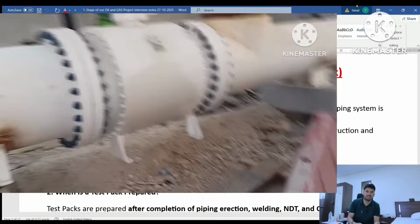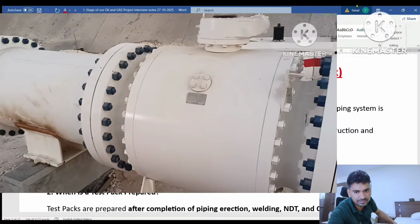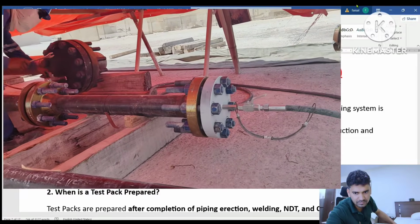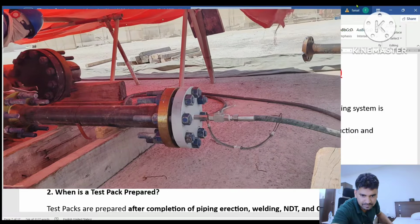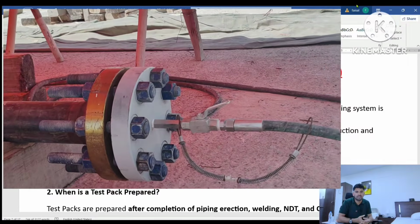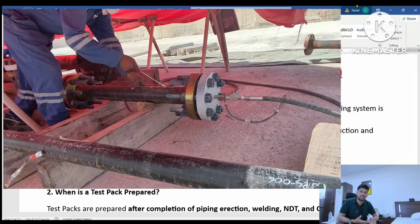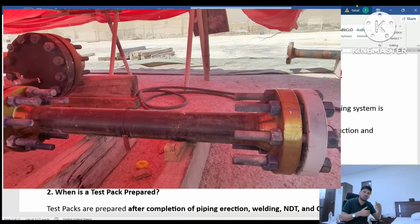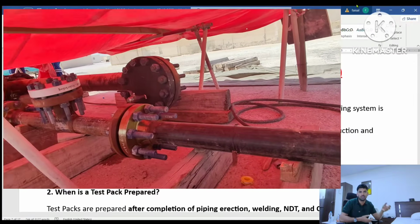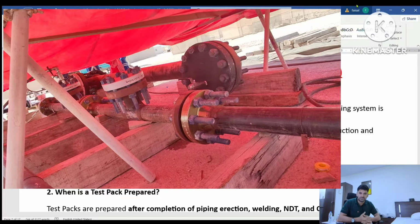On the basis of this test pack, you are going to check the integrity testing, the strength testing, your welding, your joints, your pipeline, your flange connections, your nozzle connections and your equipment connections. All of these are tested because of this test pack.